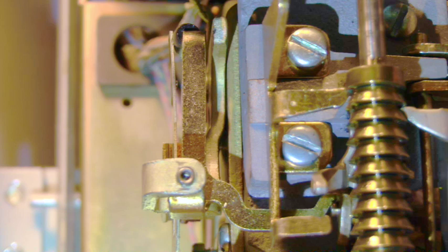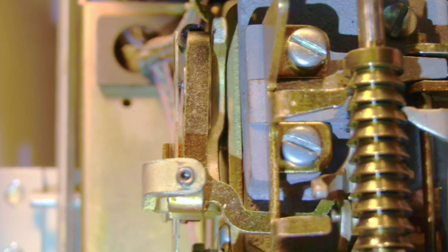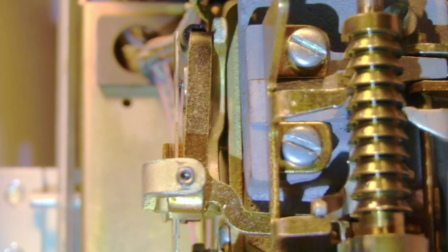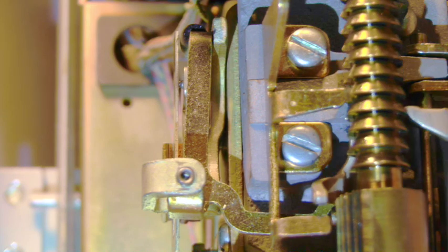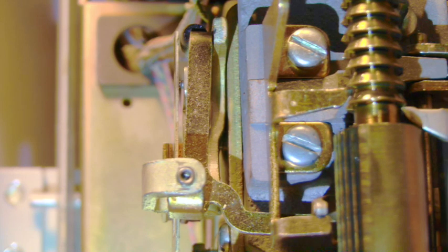Each time the armature falls back upon de-energizing of the vertical magnet, the lever pivots back to its normal position, releasing or closing the interrupter contact springs. So the vertical interrupter springs operate and release for each vertical step of the shaft. They form part of the control path for the automatic vertical stepping process.